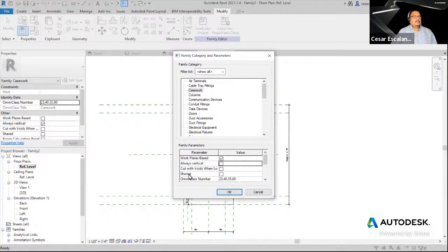Here's another one that I use at your discretion. This is called a shared parameter. Again, this dialog box is available here in this button. This share will expose the component families in the project. So if you don't want the door to be a family that you can access in the project, leave this unchecked. But if you check this, when this family is loaded into the project, the door is going to appear in the project browser as a family that you can drag and drop. So the components can be shared and made visible in the project, or you can disable that behavior.